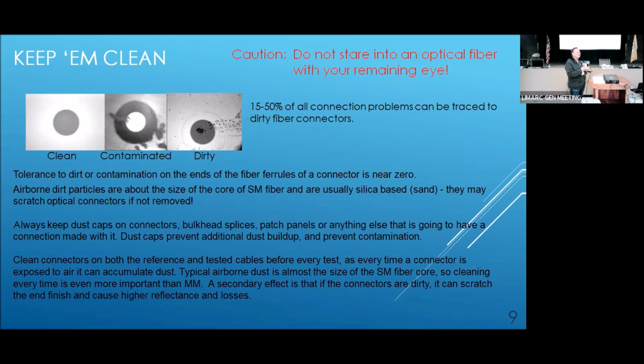George, those splices, they don't make them flat. They put them on an angle, right? So they don't get reflection of light back. Right. If you ran a flat splice, that would create a potential mismatch. You might get some reflections, the equivalent of SWR in a coaxial cable. If you do it at an angle, the cutover is much smoother, and as a result, there's less transmission loss and so on. So, right, they are done at an angle.